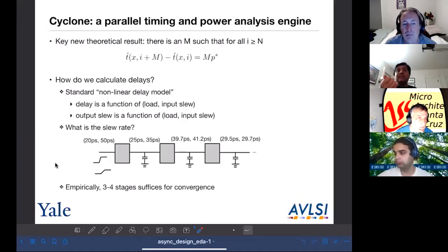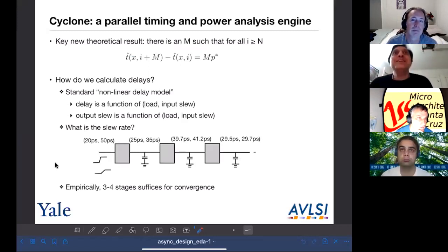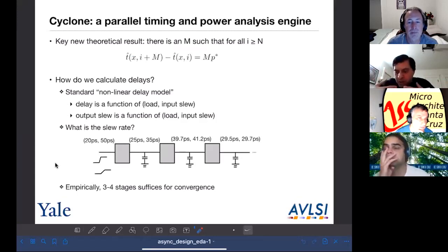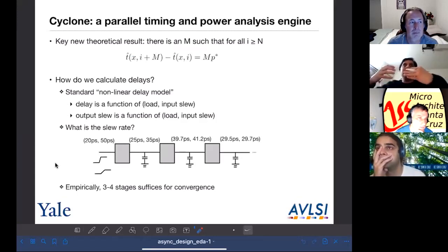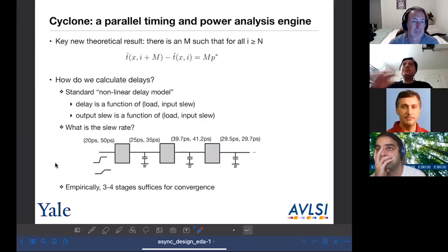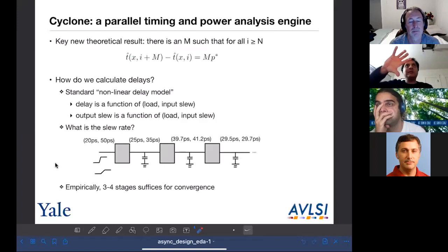But then there's a second piece, which is how does this affect the delay, right? This is not implemented yet, okay? So this is what will hopefully be added to the timing analysis engine, because if you think about what's happening, the circuit's running, and at runtime, you know what the noise is, right? Without knowing the timing, you don't really know what the noise is. So it's a coupled calculation. So what you need to do is the timing analysis and noise in one pass, coupled. So that's what's going to have to happen.